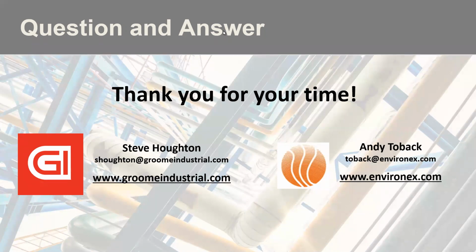I think that measuring your ammonia slip at the stack is a good indication if your plant doesn't have to do it continuously. And that's kind of what happened for case study 2: that plant isn't required to measure ammonia slip continuously, did some diagnostic testing and said, we're looking to increase some efficiency here. So that would be a great indication that your unit would be a prime candidate for tuning. The other thing that we would want to look at is what your inlet NOx is and what your relationship to your ammonia flow and inlet NOx is.